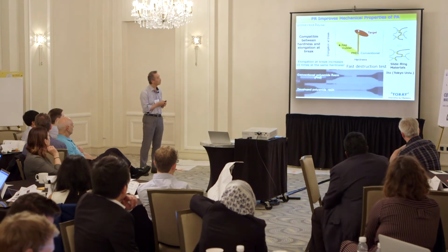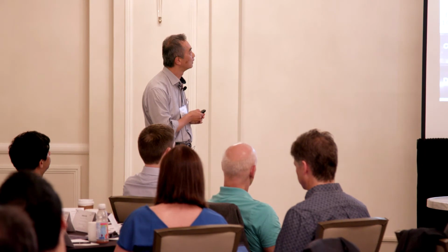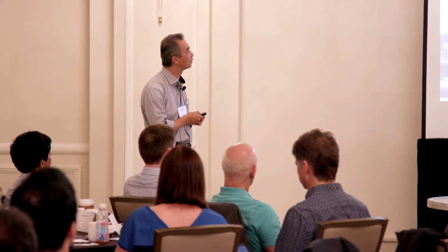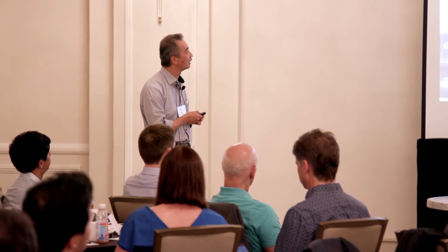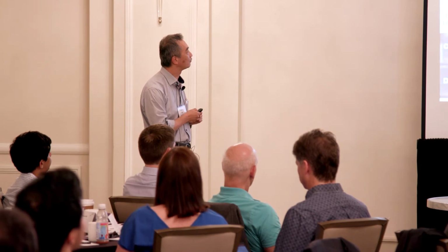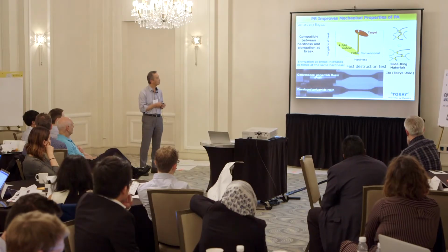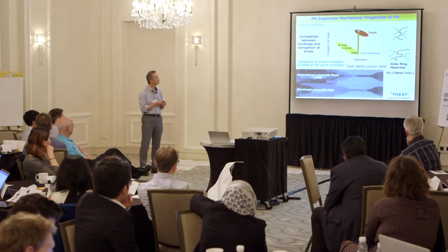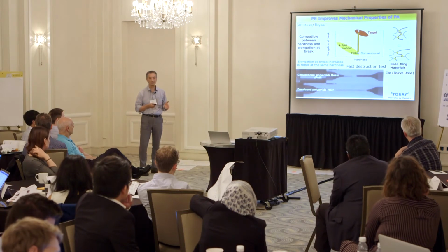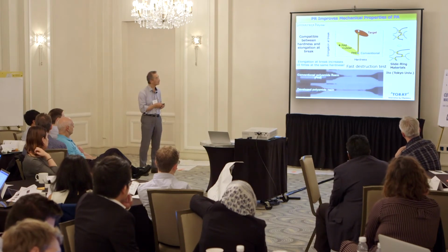Toray improved the mechanical property of polyamide resin by introducing the polyrotaxane. You know the hardness and the elongation at break have a trade-off relation. Sometimes they incorporate some small rubber spheres in the polyamide resin.